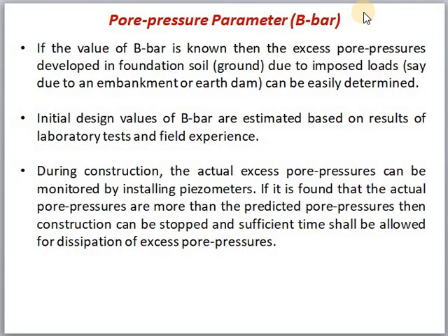So if you know the pore pressure parameter B bar, you can find the excess pore pressure developed in the foundations or in the field. Okay, and initial design values of B bar you can estimate based on laboratory tests or based on the field experiments, obviously. And during the construction, by the use of piezometers, you can actually measure the excess pore pressures.